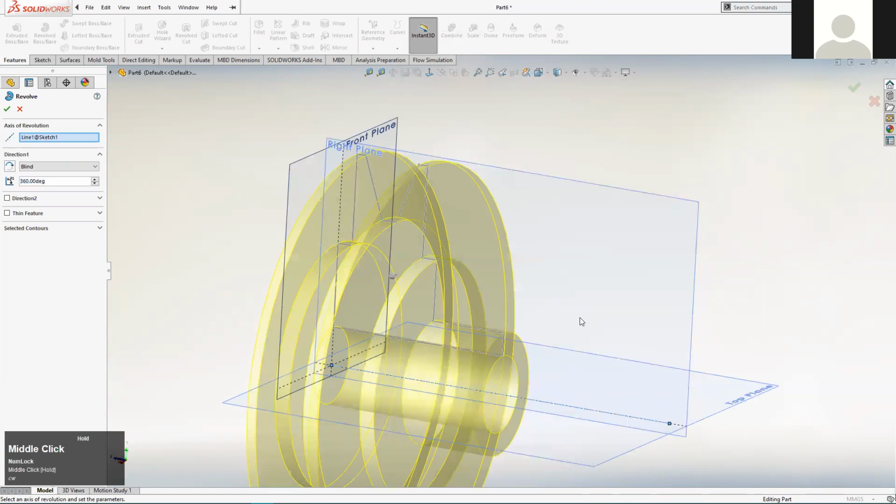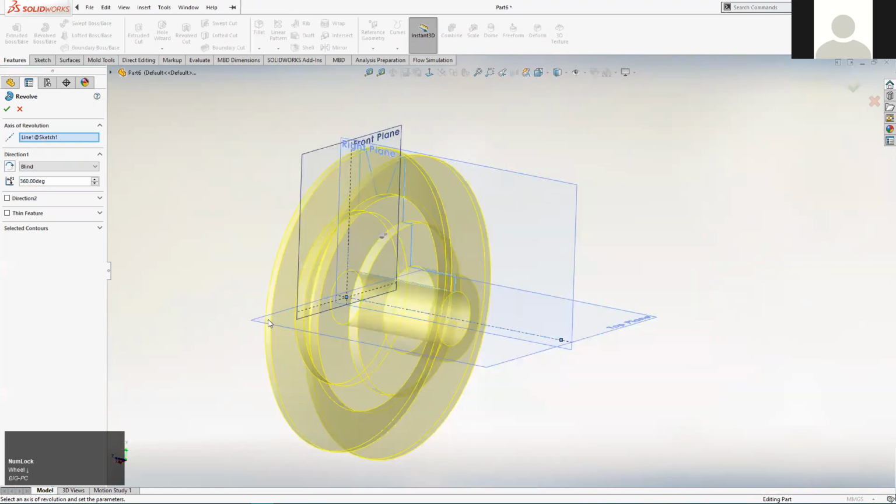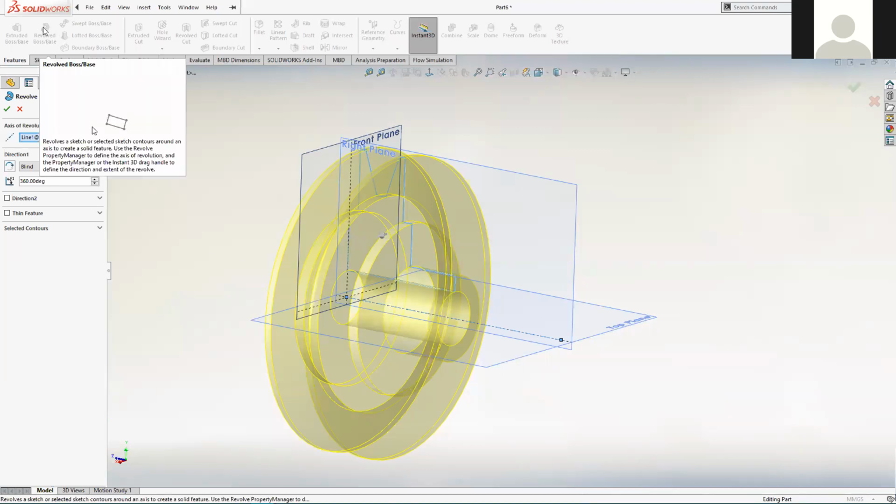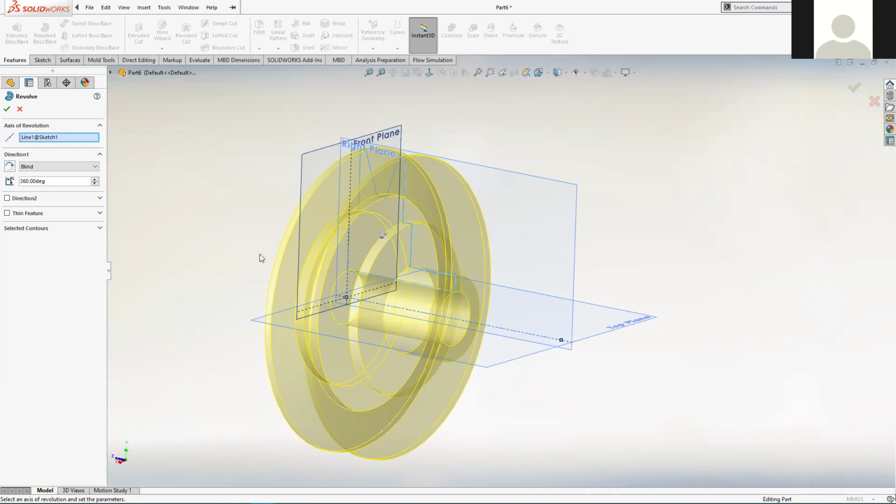Here's your preview of your revolve. So you can do it either way. If you have a pre-existing sketch, you can pre-select it and then initiate your feature. And if the sketch is suitable, the system will accept it as an input. And if it's not, it will give you an error again. But that's a different method of working if you already happen to have created a sketch in isolation, not as part of a feature.